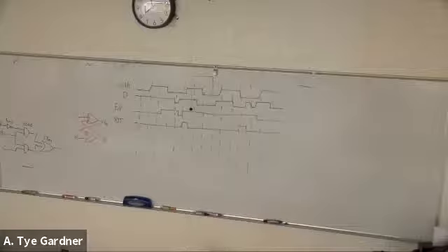The next time that anything can change, because I don't have to worry about it if I'm doing a synchronous reset, is the clock edge. Well, I'm no longer resetting, which is good. I am enabled. My D is 1, so we go 1. Same idea, reset, not resetting, enabled. Uh-oh, what happens if I'm directly on the line? Maybe I'm enabled, maybe I'm not.